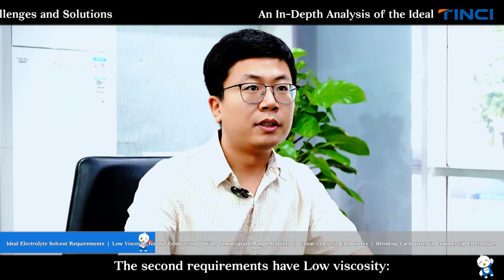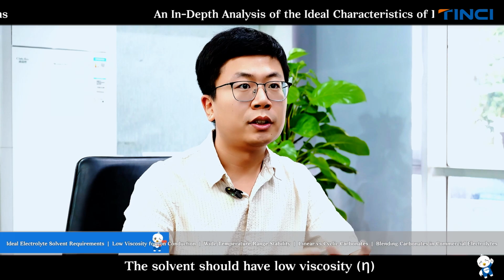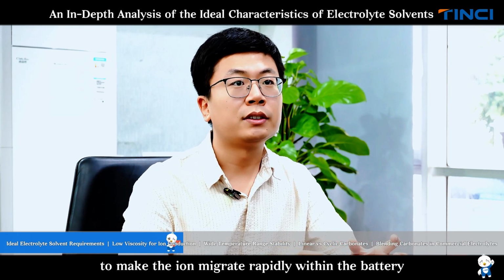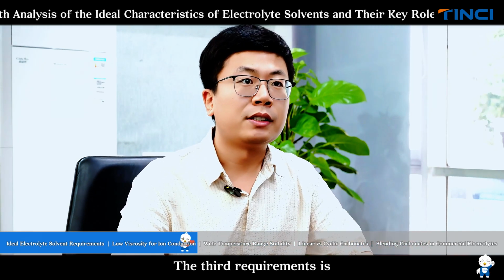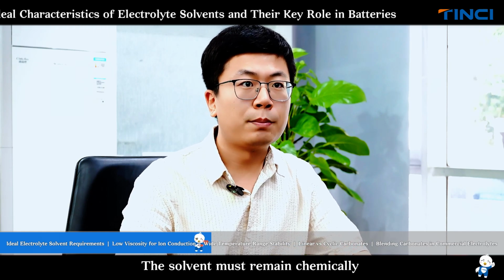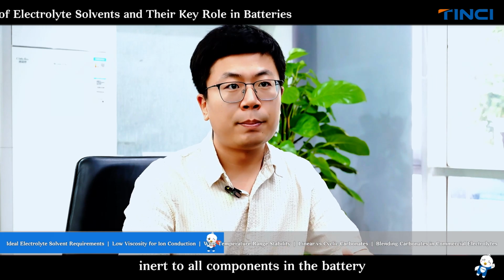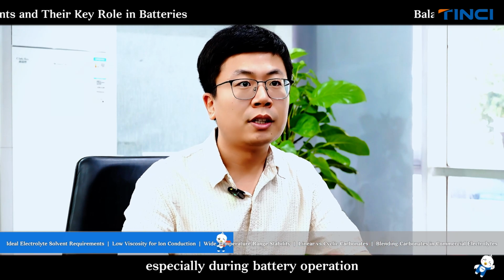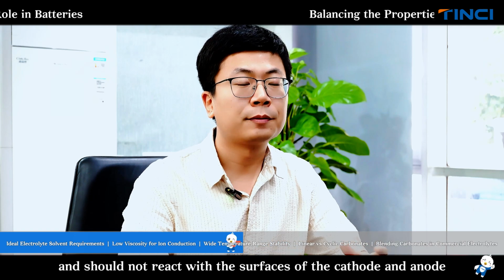The second requirement is to have low viscosity. The solvent should have low viscosity to facilitate the conduction of ions, to make the ions migrate rapidly within the battery. The third requirement is chemical inertness with battery materials. The solvent must remain chemically inert to all components in the battery, especially during battery operation, and should not react with surfaces of cathode and anode.